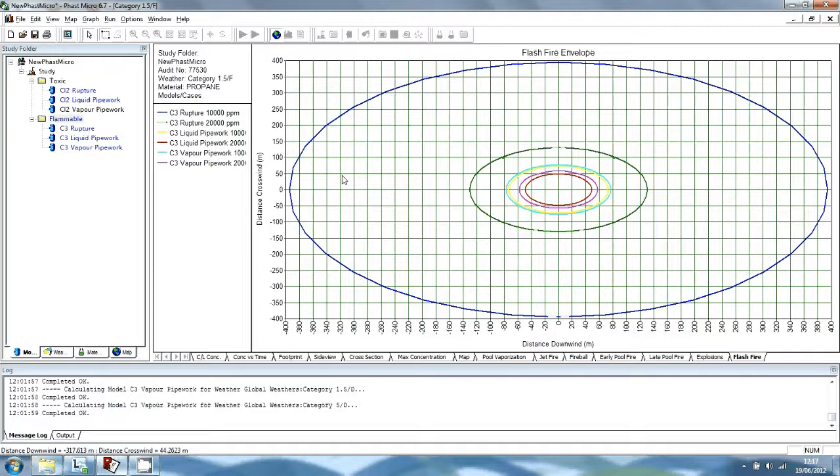There are many hazardous events that could be modelled for the tank wagons, including leaks during the unloading process. This tutorial will consider only the rupture of a wagon under normal operating conditions, a leak from the liquid side of a wagon, and a fireball produced by catastrophic rupture of a wagon under flame impingement. All events are assumed to occur while the wagon is at the unloading point 100 metres south of the propane sphere. We will now define the rupture of the wagon.